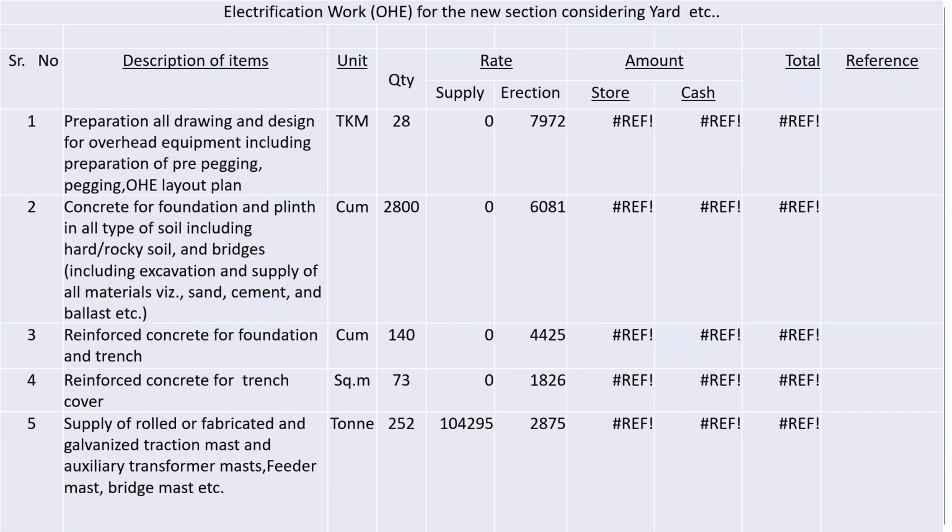Now, where you have to provide sectioning, that is also a main thing. This design aspect and this estimate your sectioning idea. Mainly we need sectioning in the station area, in the mid section. In DFCCL it has been fully avoided, but in existing systems, when converted into 2x25 kV, at that time we are converting the single pole isolator into double pole isolator. So all these things you have to keep in your mind.